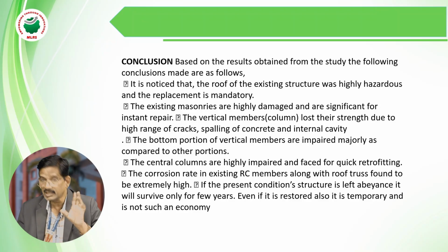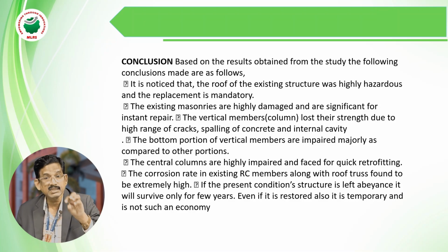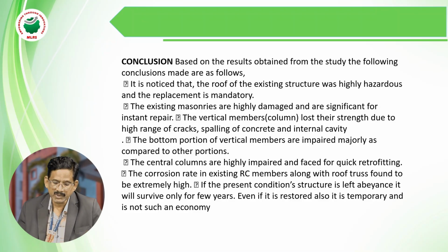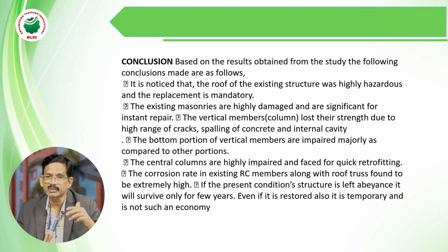Next, the vertical members, the column members, lose their strength due to the high range of cracks, spalling of the concrete, and internal cavities also. Internal cavities occur because of the stresses developed by the corrosion of the reinforcement. The bottom portion of the vertical members is impaired majorly compared to the other portions.